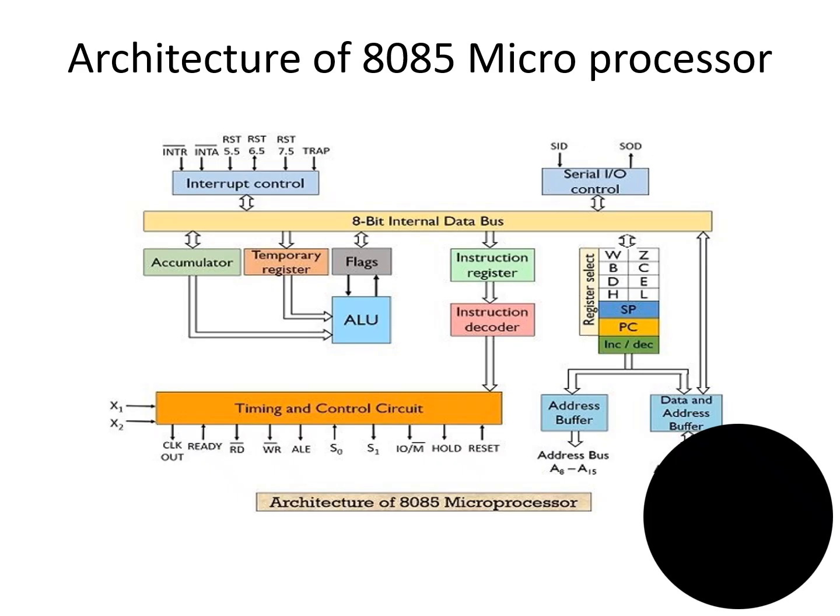Individual registers are 8-bit registers. Combining these registers, we call them a register pair, and a register pair holds 16-bit data. So BC register pair, DE register pair, HL register pair. We have three register pairs which can be used to hold 16-bit data.